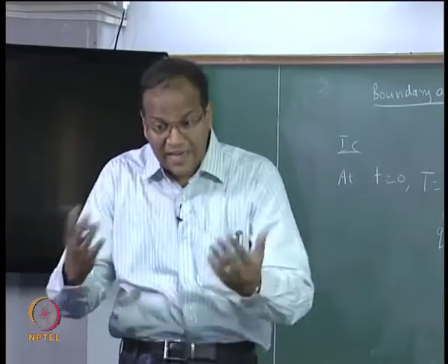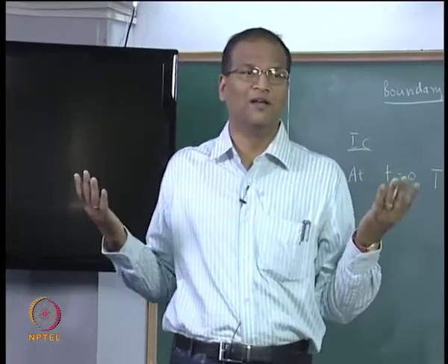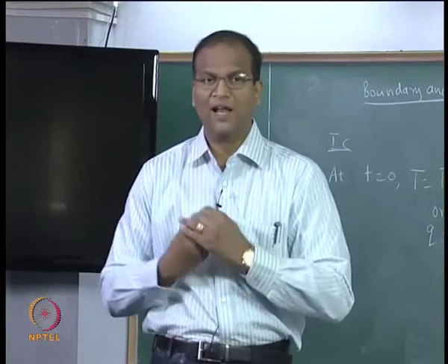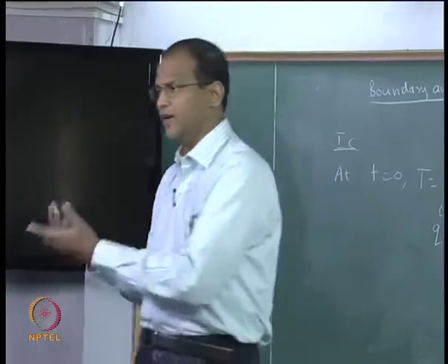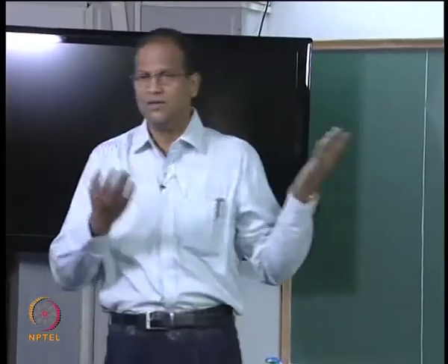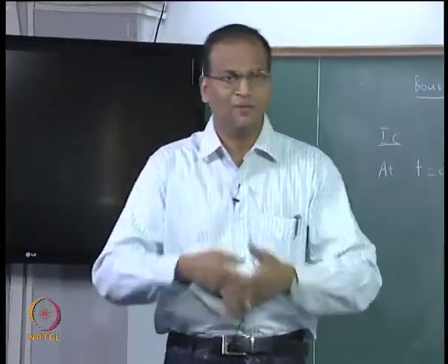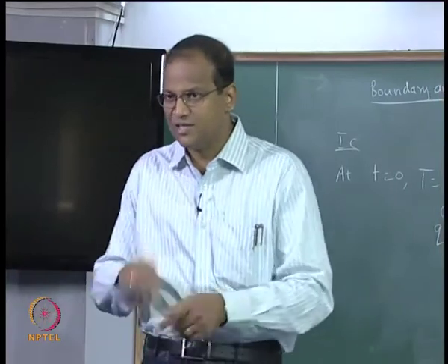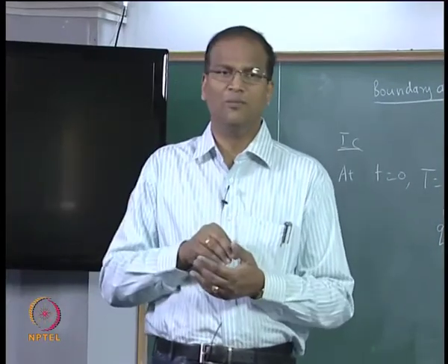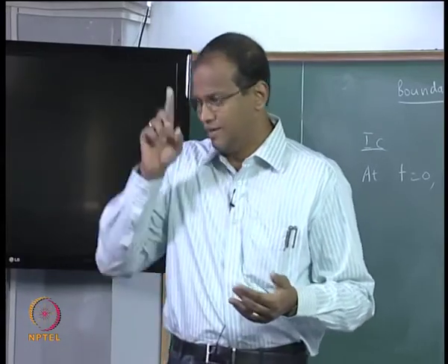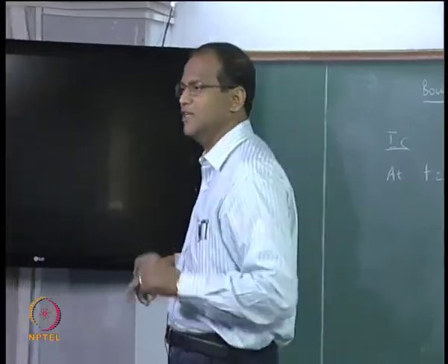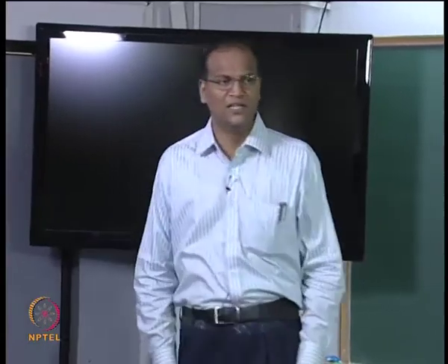Once you have this, then you go to the problem and now you take recourse to mathematics. Okay, can I analytically solve it, numerically should I solve it, finite element, finite difference, finite volume, Fluent, COMSOL, STAR-CD, I will write my own code, MATLAB, all these things will come. The first is you have to sit down before going to the computer, sit down with paper and pencil, write down the governing equation, conceptually get a hang of the physical system, identify the various boundary and initial conditions.